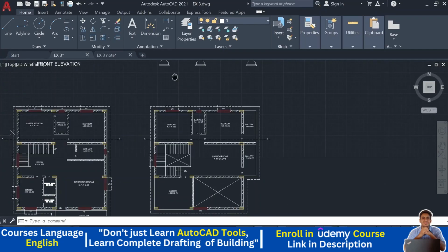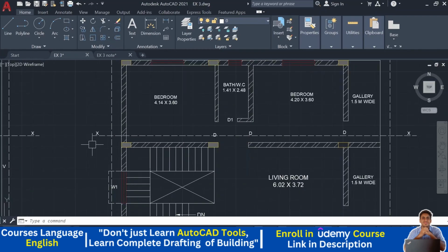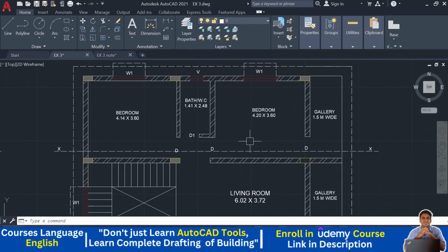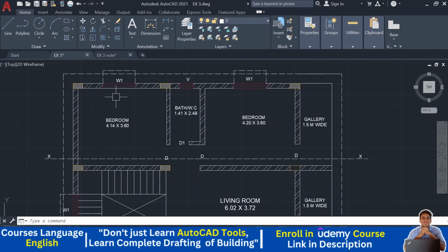So now we see how to do the section in the first floor, okay. So we have taken this section. So here 1 2 3 4, again the four walls are there, and what all things are visible here: this window, this one extra door, and from this door we can also see this ventilator, then this window, and then this door, and then this gallery, and after the gallery we need to show the slab projection.